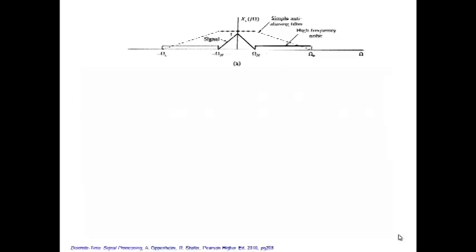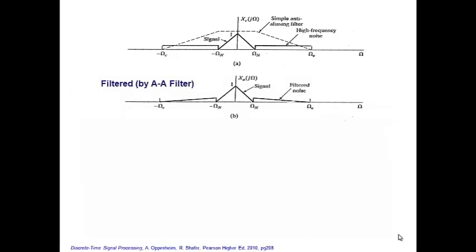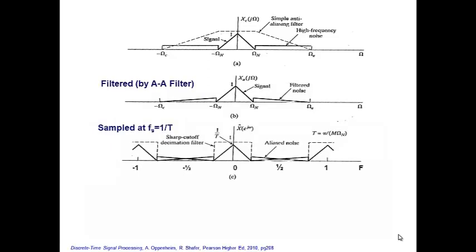or we do this. We use the same low-cost filter and alias, and you use a sampling rate that's chosen not quite to be as high as I thought I was going to need there. I'm going to let it alias, and then I'm going to use a digital filter to throw out the alias stuff, because I can make a digital filter a high-order digital filter very easily. And so we'll do that.